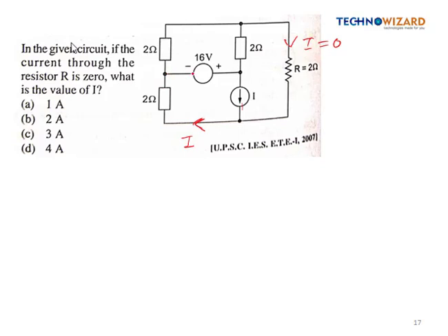So here some current, suppose I1 current is flowing in this direction, then by the KCL, if I current is coming and I1 has gone this side, from here I minus I1 current will flow. Now from here 0 current is flowing, it means the entire current I minus I1 will flow in this direction, right? So we have obtained the value of current in each branch.